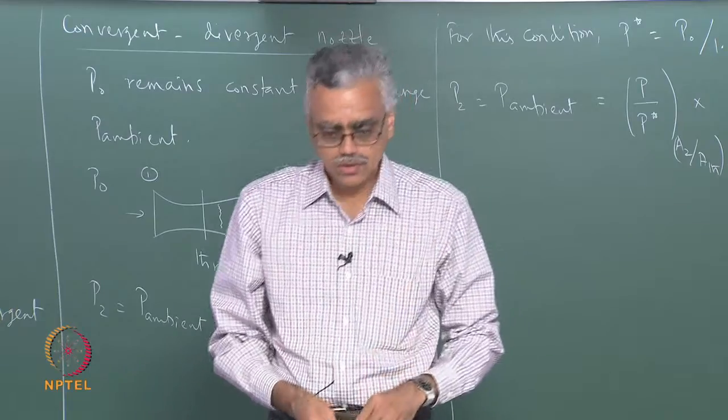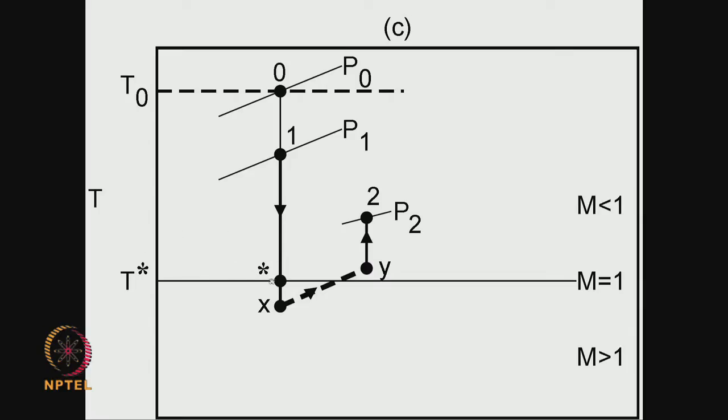Now also notice that the process curve from 1 up to the throat remains the same as before. It cannot change anymore because M is already equal to 1 at the throat even in the previous case. So that means any change in the downstream pressure will not be able to propagate upstream of the M equal to 1 location, the sonic state. Which means that the mass flow that comes through will also remain the same. It is not going to change anymore. The same mass flow rate is going to go through now.